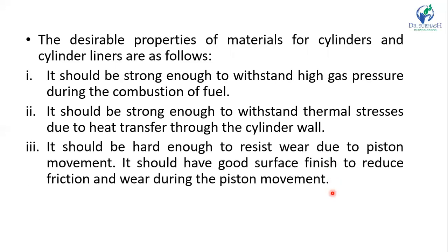Okay, and it should be hard enough to resist the wear due to piston movement, and it should have a good surface finish to reduce the friction and wear during the piston movement, and it should be corrosion resistant. So these are the desirable properties of the material of cylinder and cylinder liners.